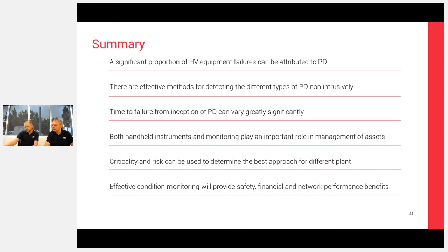Six months, annual for medium consequences, when you're referring to online periodic testing. We're not talking offline. When we're talking about the periods, we're effectively talking online. It's quite interesting. In Australia, there were lots of companies who would say they were going to test switchgear every 12 months offline.